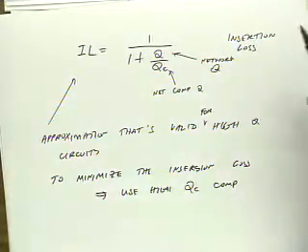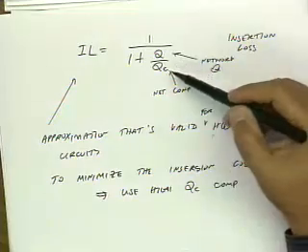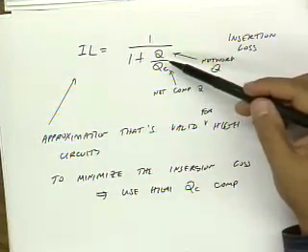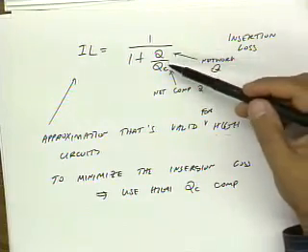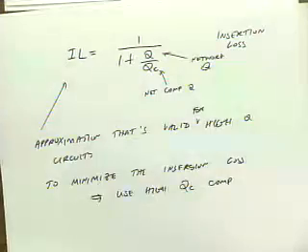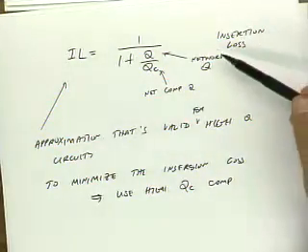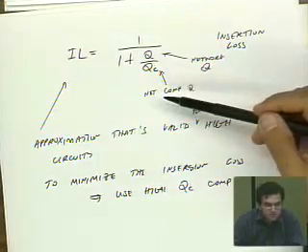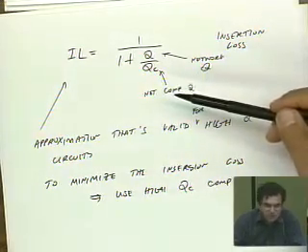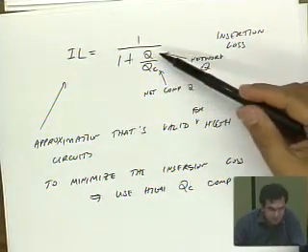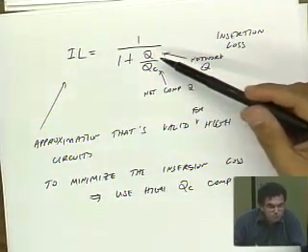But what's important is it's not the absolute quality factor that matters, it's the relative quality factor, relative to the network Q. So if someone tells you, hey, I'm designing a matching network and my quality factor is 2, should I use a QC of 1,000 or a QC of 100? Well, you would say, don't spend your money on that expensive component that has a QC of 1,000, because your network quality factor is only 2.